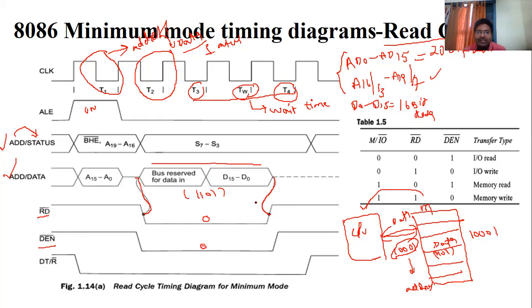So the microprocessor has not yet taken the data. It is available on the bus, on these lines only, and it is not coming back to the CPU yet. Once it is available, the microprocessor generates data enable, because it checks whether the available data is correct or not. Once it is correct, the microprocessor performs the data transmission and reception.